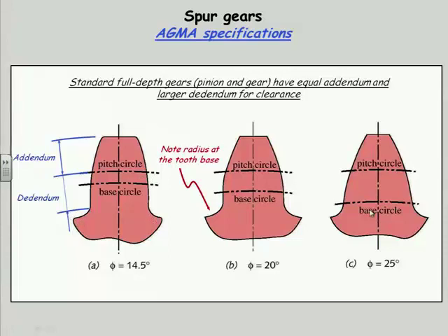So you can see the advantage of the larger pressure angles. Now, the larger pressure angle, of course, means I have a larger component toward the center. But I trade that off against more meat in the gear tooth, so I'm less likely to break with the same force or even more force tangentially. So that's the reason that the recommendation nowadays is to go toward the larger pressure angles.